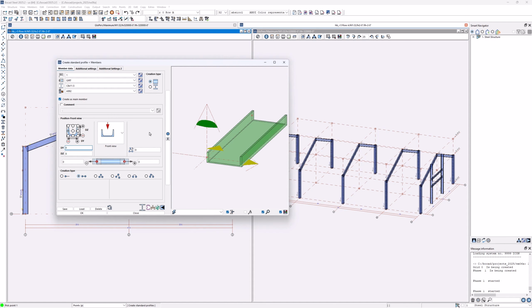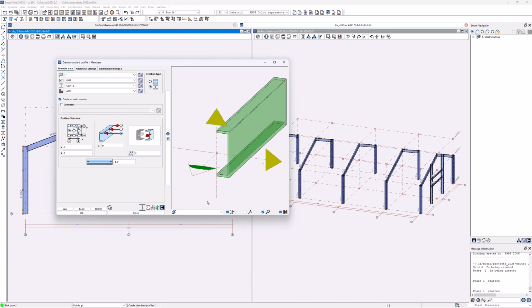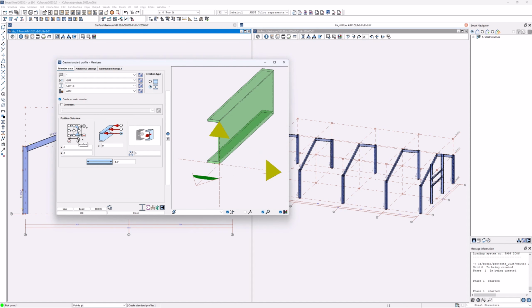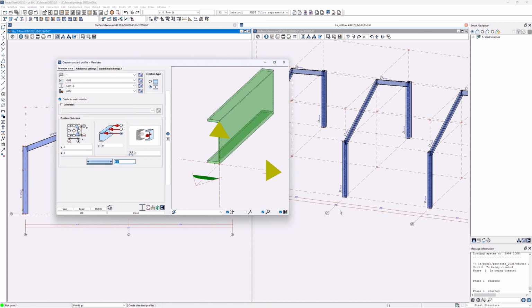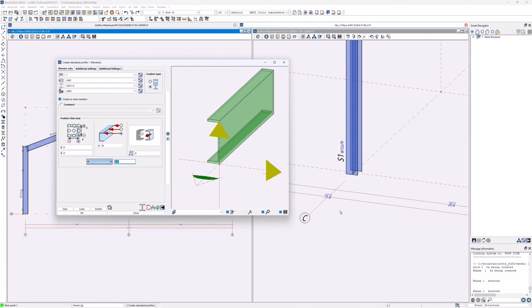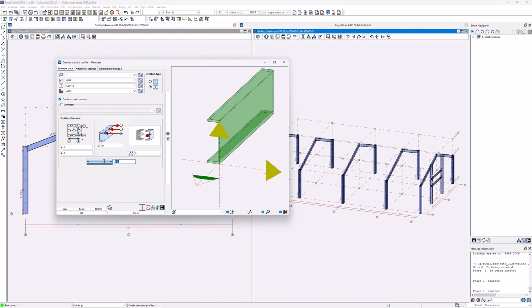Let's bring it back to the picking point, and I'll create these perpendicularly to my view. I will use the corner, the back corner of the girt. What length do we have? I can split them up later. This is more about profile creation. 73 feet 8 inches, so I'll say it is 73 feet 8 inches. It's away from me.